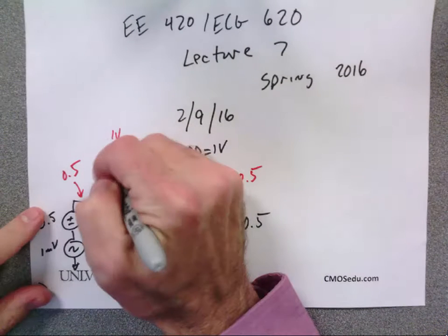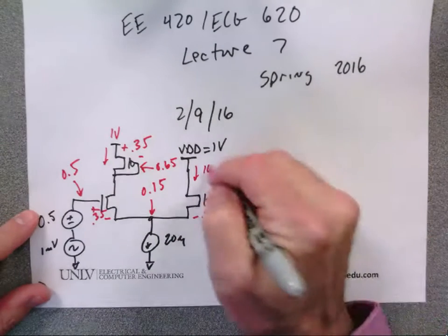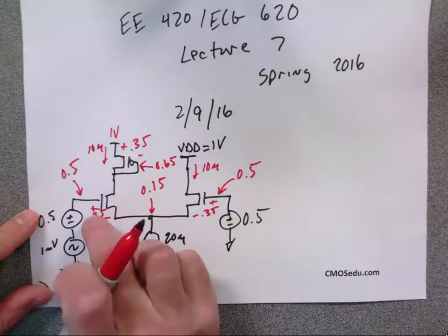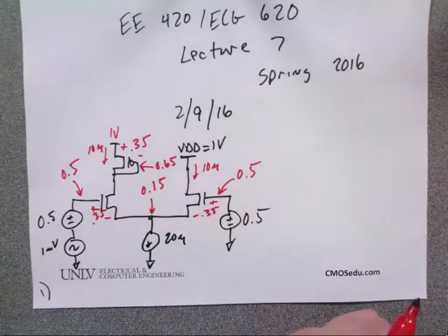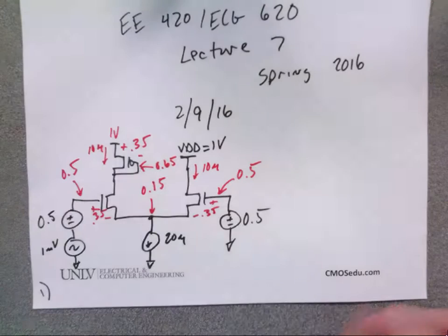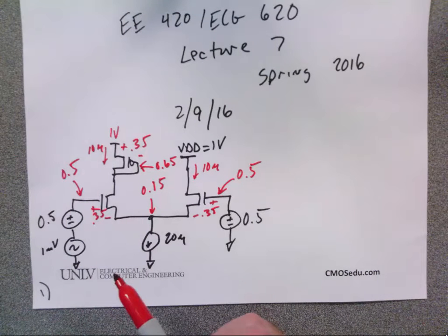What are the currents through here and through here, DC? What's the relationship between here and here? What are the VGSs of the two NMOS? What is the DC? We're talking DC. What's the relation between the DC VGSs? They're the same. I don't ask hard questions. Okay?